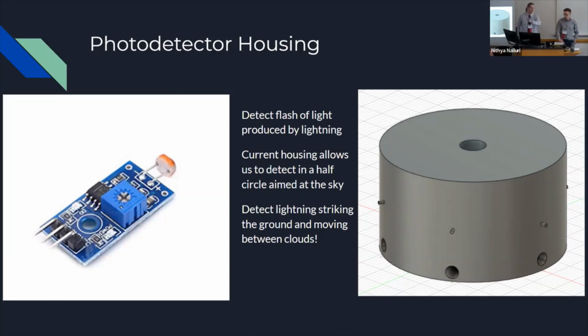So we can see all around it and above it, but we're not detecting anything below it, so we don't get arbitrary flashes from reflections from car lights or anything of the nature. So you could put this up on a pole, nice and high up, like 10, 15 feet. You lose a lot of false positives.